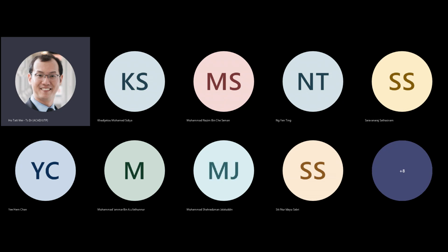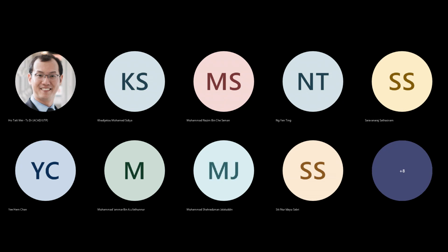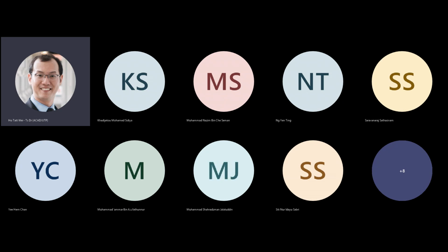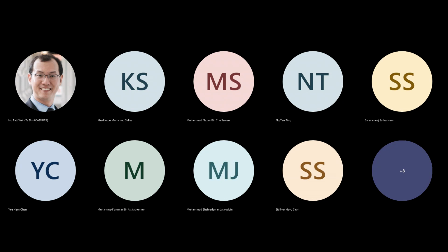And the basic equation for the capacitance is proportional to the area. That means this part here, the area here. So what is the area here? The area corresponds to the length times the width of the transistor divided by the distance, the oxide thickness. How thick is the oxide layer you're growing?